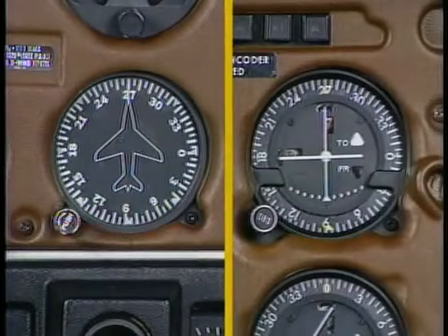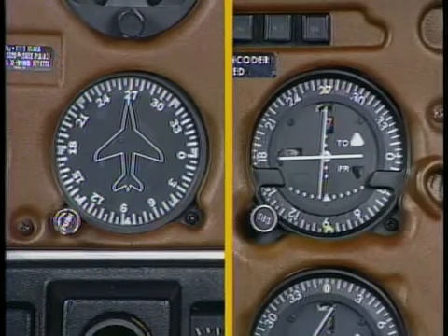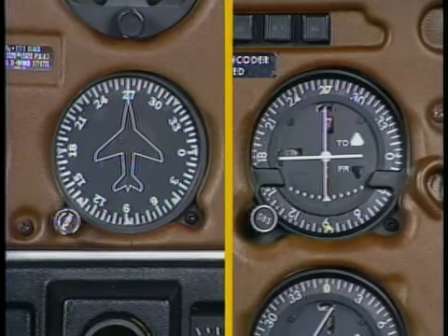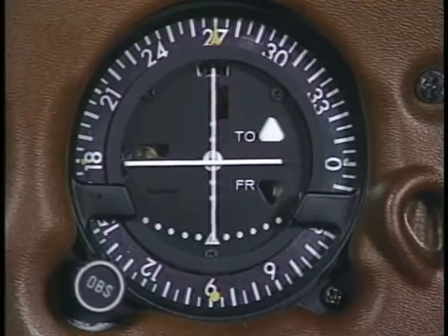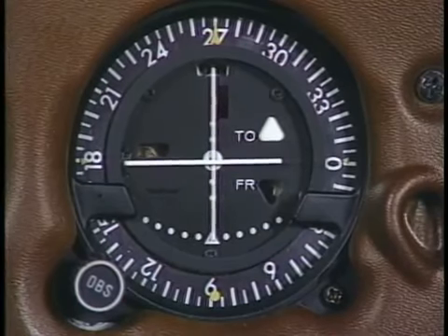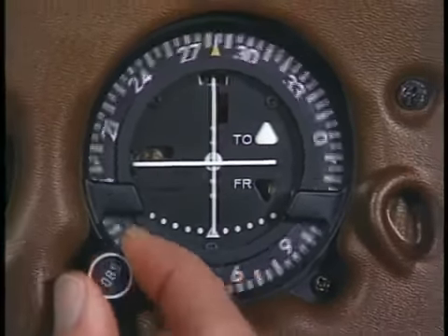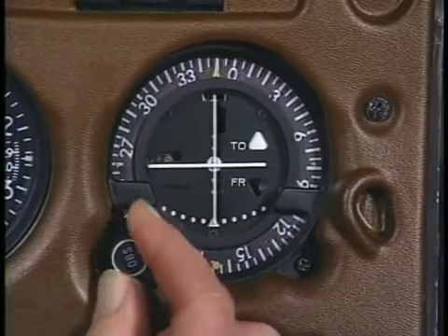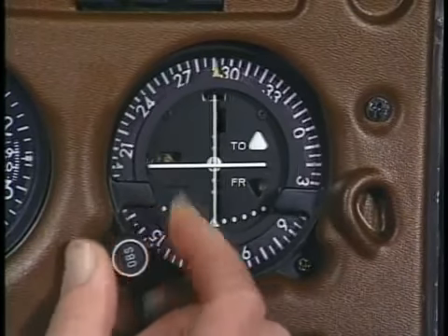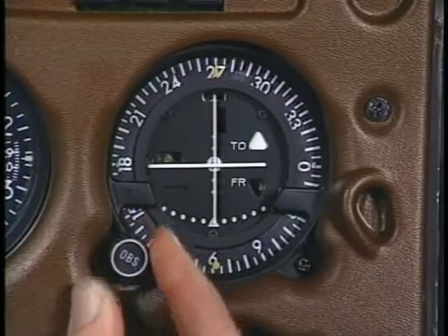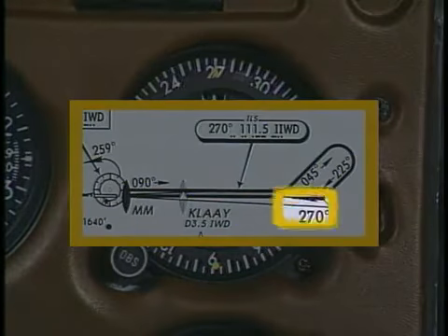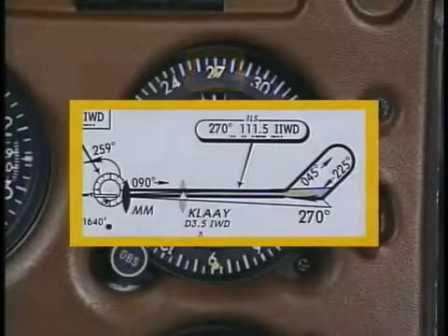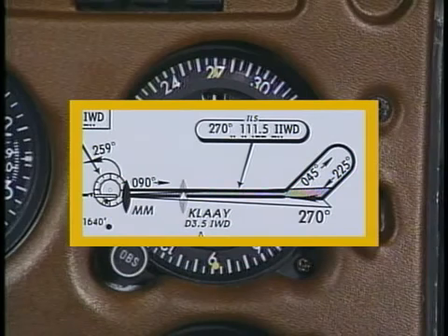With increased sensitivity, the CDI reacts more rapidly. Therefore, you will need to make smaller course corrections and make them more promptly. A unique characteristic of the localizer signal is that it provides only one magnetic course to the runway. This means that no matter where you set the OBS, the needle senses your position only in reference to the specific localizer course. In actual practice, it's a good idea to set the published ILS course on the azimuth ring as a reminder of the proper course and to help with heading corrections.